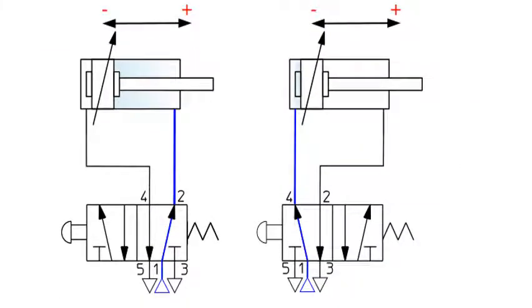Look at this diagram, where we can understand extension and retraction by using some valve attachments. See here, there is one blue colored line. This blue colored line indicates the pump line. This one is connected to the pump.